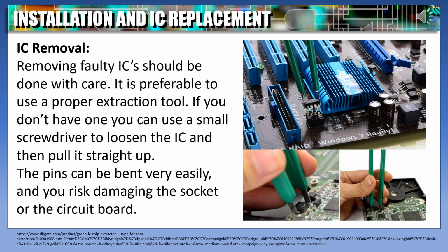Removal of faulty ICs should be done with care. It is preferable to use a proper extraction tool. If you don't have one, you can use a small screwdriver to loosen the IC and then pull it straight up. The pins can be bent very easily, and you risk damaging the socket or the circuit board.